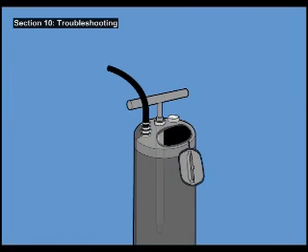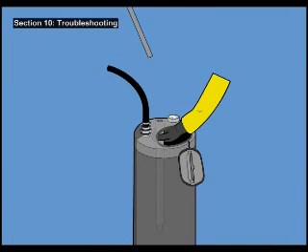Section 10. Troubleshooting. On some occasions, the sprayer may not work as expected. If the pump fails to pressurize the tank, remove the pump plunger from the sprayer by loosening the nut holding the pump on the top of the tank. Insert a gloved hand into the tank and hold the pump cylinder. Unscrew the cap holding the pump and pull the plunger from the tank.